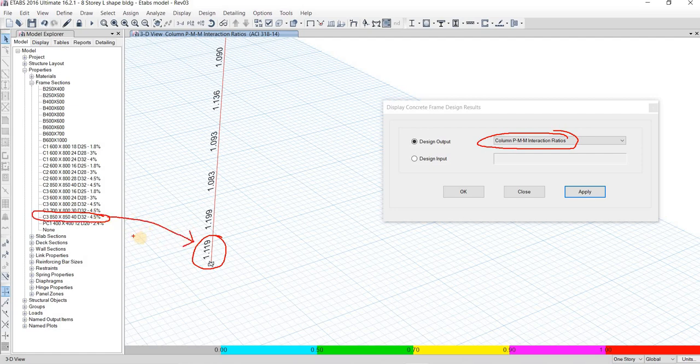So meaning our column is undersized, but you can make it 4.5. You can make it 6 from the code. But as a designer, I am also considering the construction status, or that this is very congested, and if you have a splicing zone of 30% or 1/3, at that level you splice the 1/3 of the reinforcement, and at that section you will now get 6%.